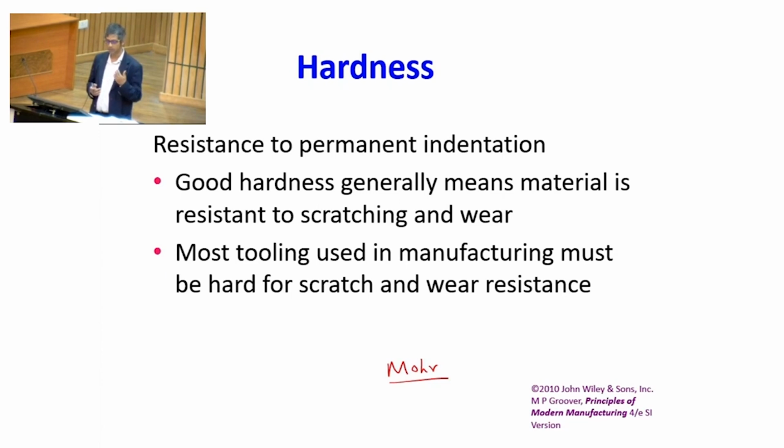resistance to wear, plastic deformation, even scratching. You know the Mohs scale, right? That is why actually scratching can be used to measure hardness. In the Mohs scale, diamond has the highest hardness, talc has the lowest hardness, in between you have 10 different materials present.